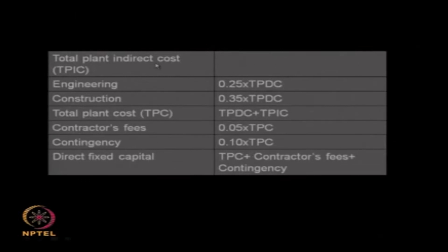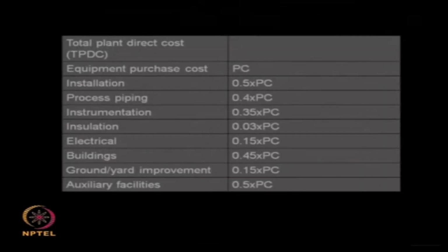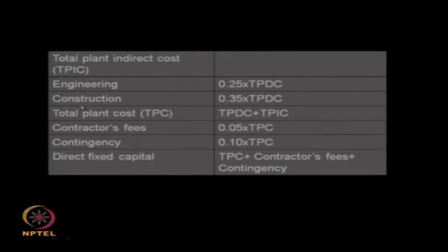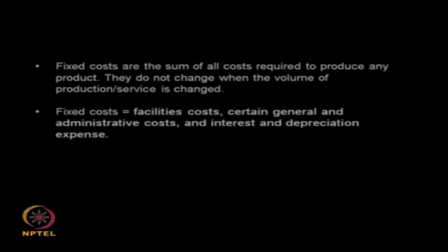That is the direct cost. Now you are also going to have indirect cost. That means you need to pay your contractor, your construction agency, the engineering agency and so on. They all get added up as well, and these also contribute towards the actual equipment cost. So equipment cost does not just include the cost of the equipment you buy from a vendor, but you need to consider all these aspects. So it gets doubled or even sometimes tripled relative to the actual cost of the equipment.